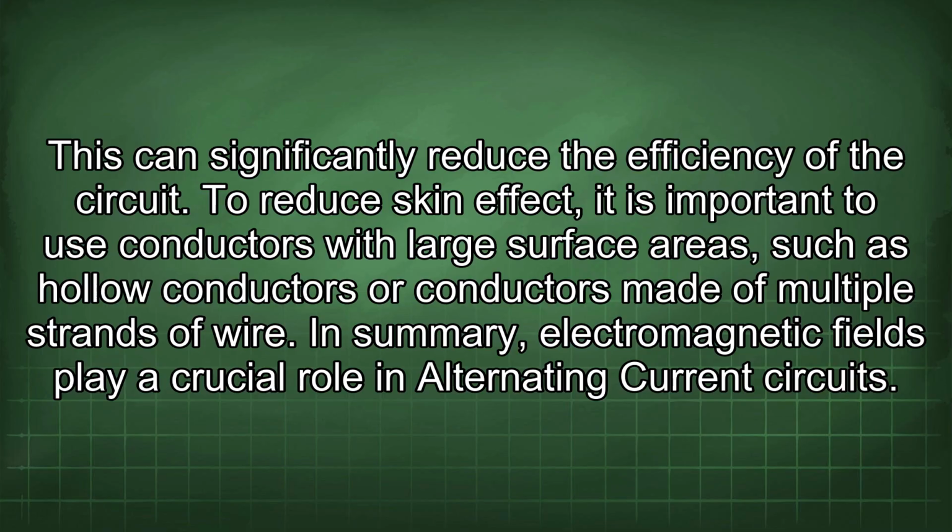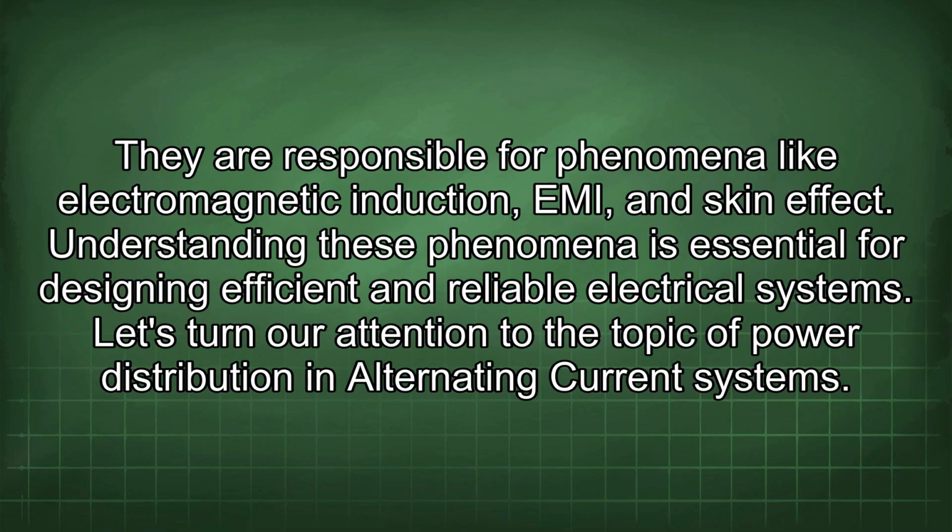To reduce skin effect, it is important to use conductors with large surface areas, such as hollow conductors or conductors made of multiple strands of wire. In summary, electromagnetic fields play a crucial role in alternating current circuits. They are responsible for phenomena like electromagnetic induction, EMI, and skin effect. Understanding these phenomena is essential for designing efficient and reliable electrical systems.